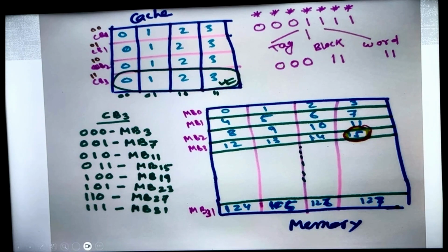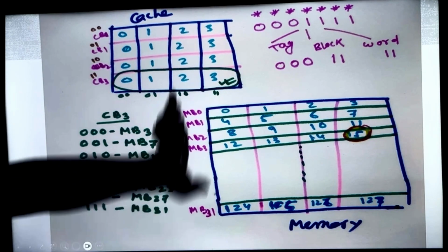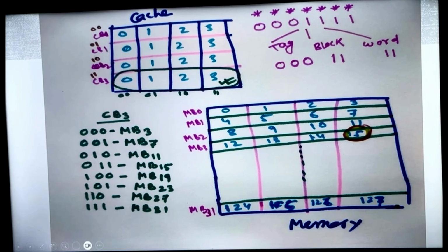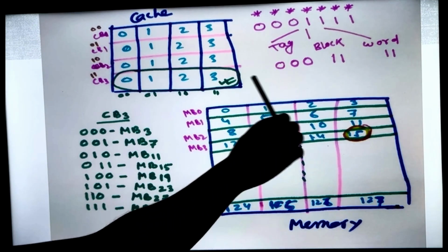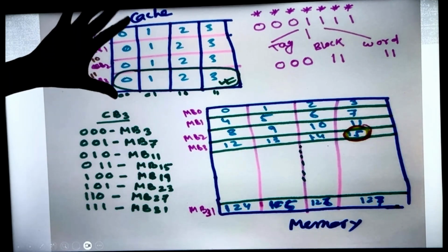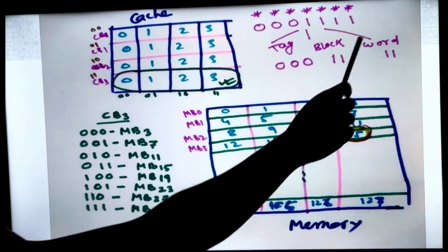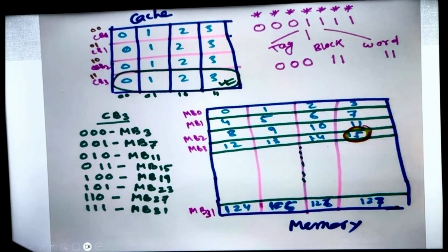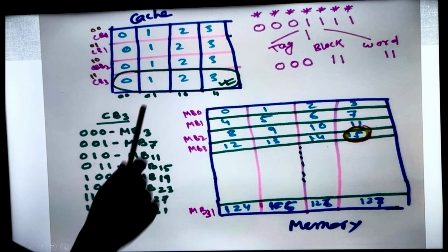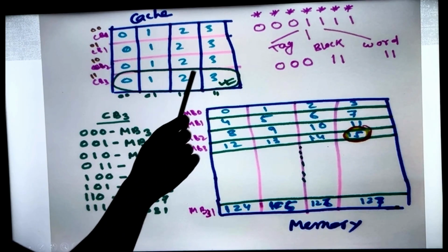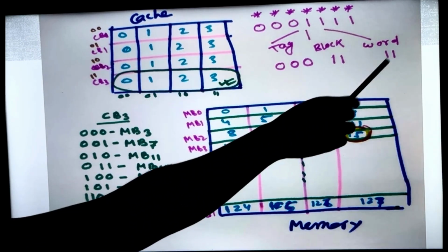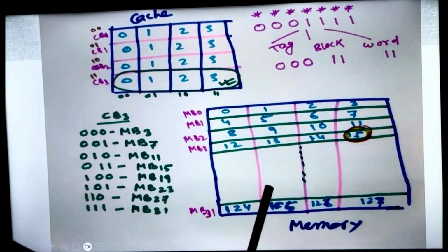So I hope you understood whatever I am explaining. Now see the magic. From this partition, your cache will easily identify that, I don't know what the data is, but I know I have to go for word number 11. Which one is word number 11? The last word, right? 0001111. It may be anywhere, but I know the word where I have to go. Last word.